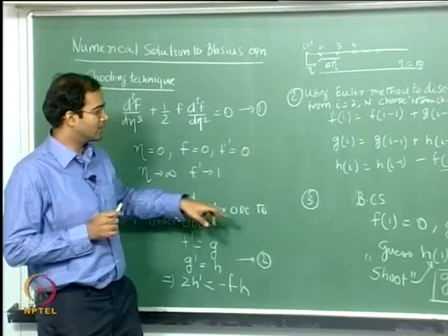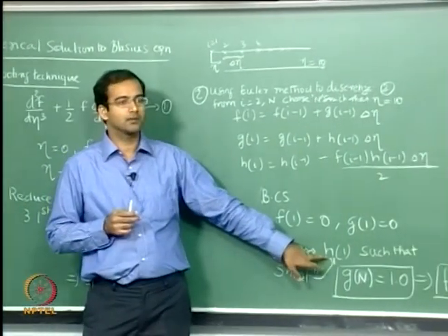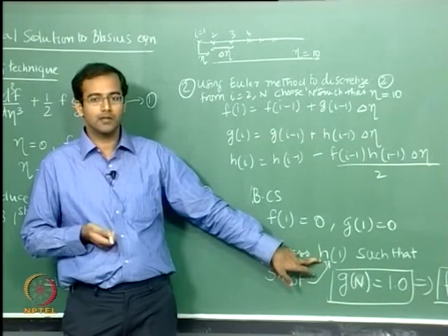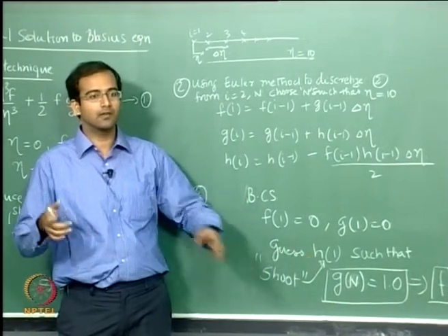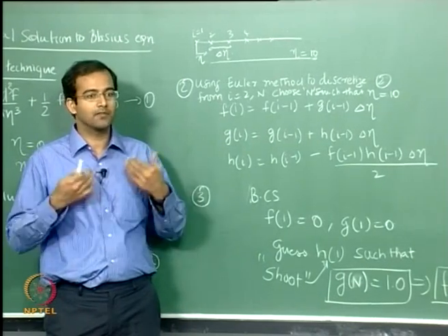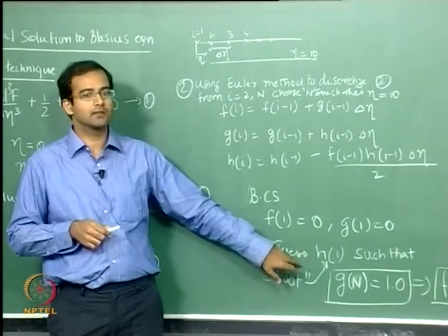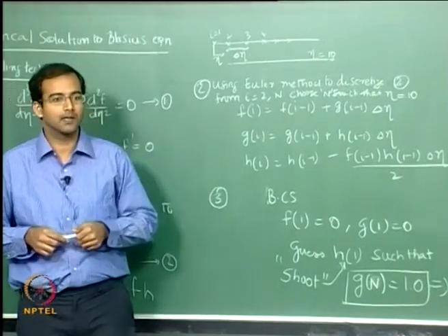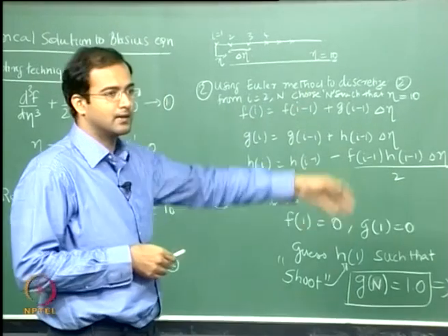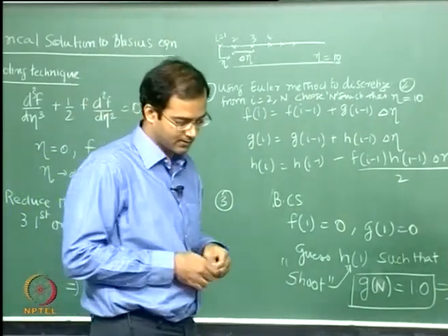Okay, so here also we don't know the value of h at 1, so h is nothing but the curvature basically, right, and Blasius also didn't know that. So he had to invent an asymptotic expansion and then match the solutions and finally find this curvature, and we are also doing it by means of guesswork, we are calculating the curvature. So the curvature is the key. Once you get the curvature, everything is simply solved.